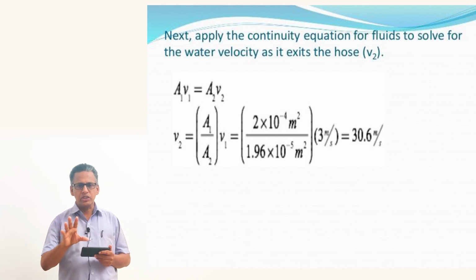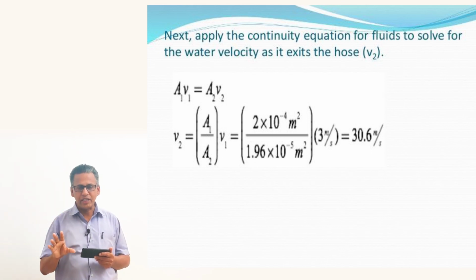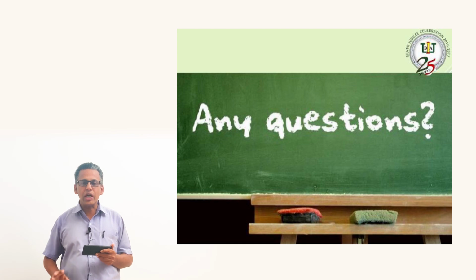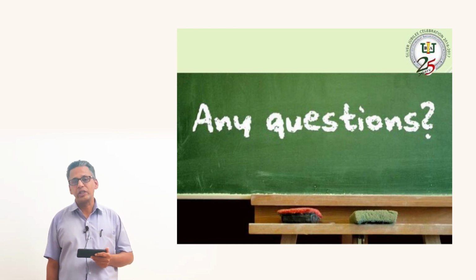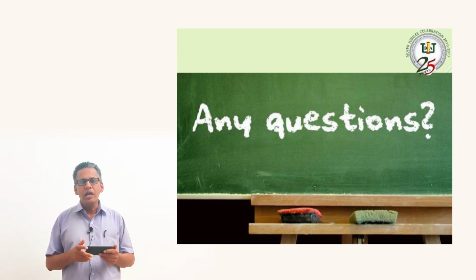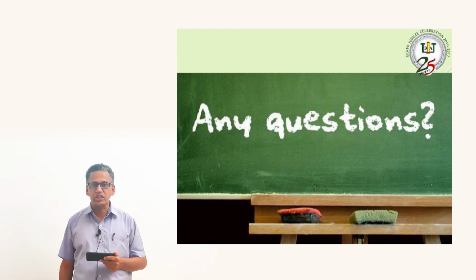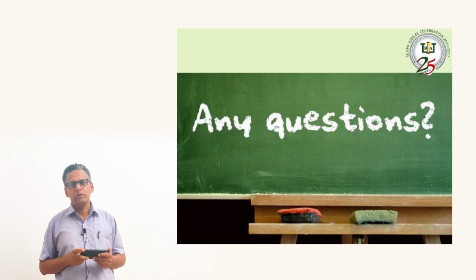So these are the portions which we discussed so far in this class, is the what is kinematics and what are the different types of flow. Then flow rate can be expressed as volume flow rate, mass flow rate, weight flow rate, and discharge or rate of flow. Discharge or rate of flow means the volume of liquid flowing through a section per unit time. It is denoted by Q is equal to area into velocity. Its unit is meter cube per second. Then continuity equation, which is nothing but a1 v1 is equal to a2 v2 is equal to a constant. Okay. Thank you.